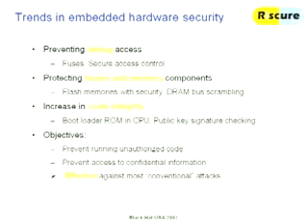And the objectives are clear. The first thing is you do want to prevent running any unauthorized code, because if you can do that, like loading it through the bootloader, then you own pretty much everything in the device. How are you going to protect your secret keys if someone can run code from the highest level from the start? So that's what you want to prevent. And then the second thing is you want to prevent access to your confidential information. So you want to encrypt it somehow, which needs a key, which needs to be stored somewhere that you can't get to.